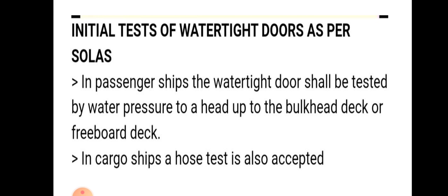So, what are the initial tests for a watertight door as per SOLAS? In a passenger ship, the watertight door shall be tested by water pressure up to a head up to the bulkhead deck or freeboard deck. In a cargo ship, a hose test is also accepted.